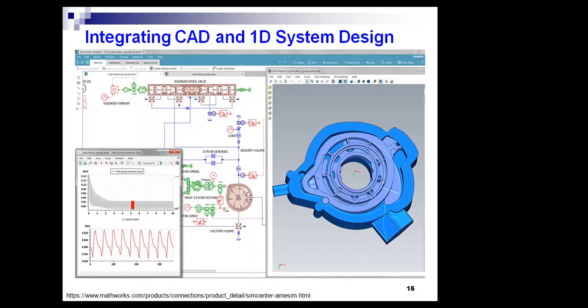The 1D environment will give output pressure with respect to time. This output will be given as an input to a three-dimensional environment in a finite element analysis, which will help us to model an appropriate environment or appropriate input conditions for the system being evaluated.